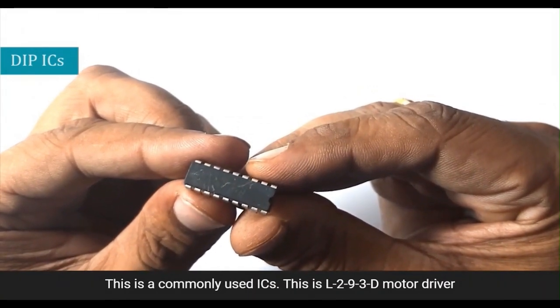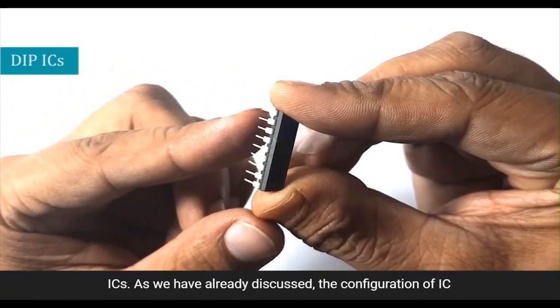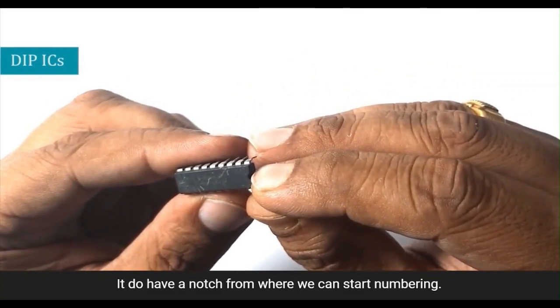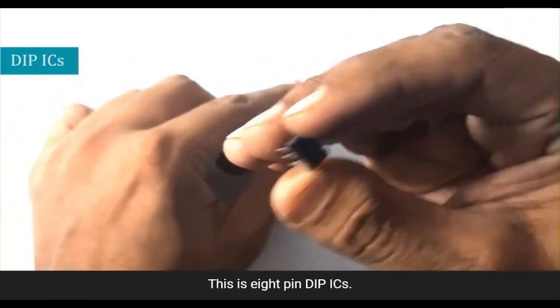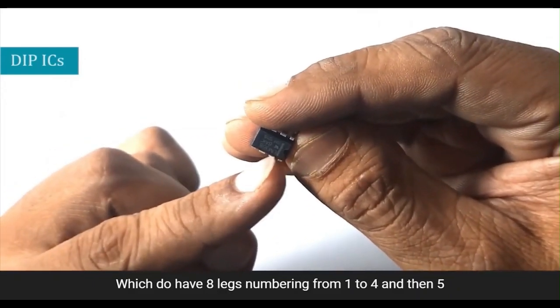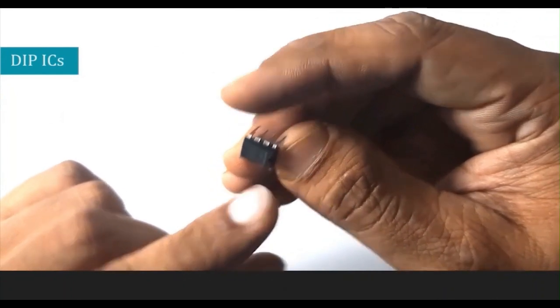This is a commonly used IC. This is the L293D motor driver IC. As we have already discussed the configuration of an IC, this IC has a notch from where we can start the numbering. I have some more ICs with me. This is an 8-pin DIP IC which has 8 legs, numbered 1 to 4 and then 5 to 8, starting the counting from the notch.